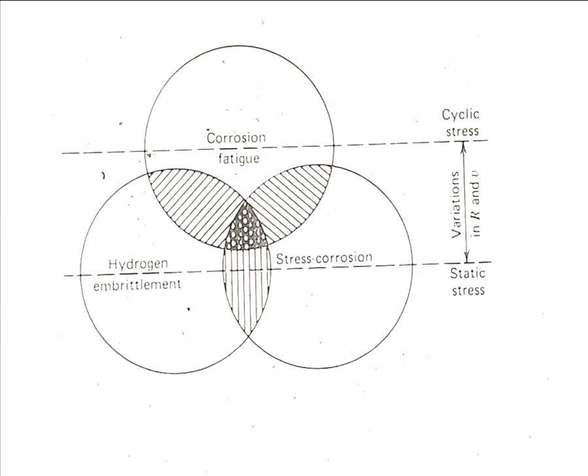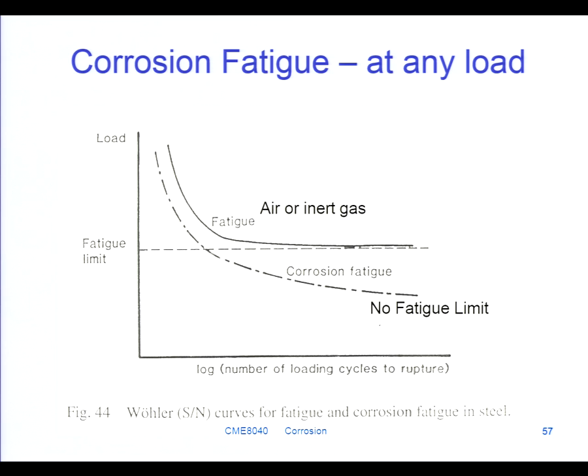This you have seen before, but it's just to remind you: cyclic loading will cause work hardening of material and may cause it to crack, and that's called fatigue. And fatigue has some particular characteristics. In steels, you find that there's a threshold limit below which the material doesn't crack, and that's called the fatigue limit.